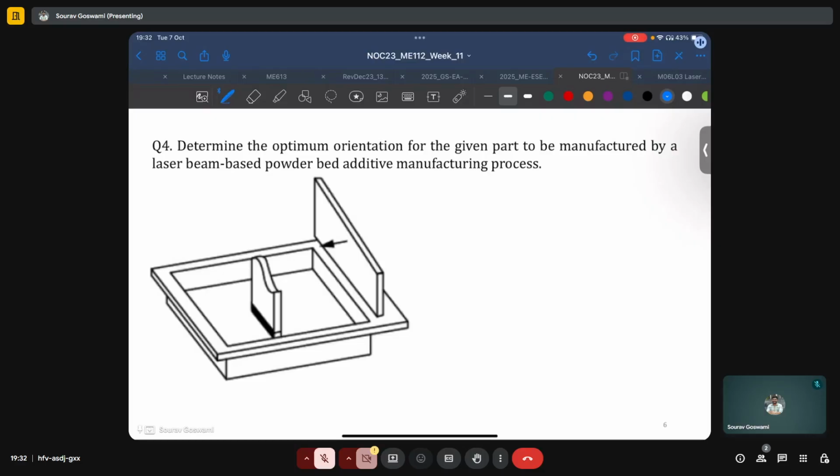One of the principles which we discussed during the session was that we should try to minimize the number of edges which are aligned exactly with the recoater blade. And the purpose for this was to reduce the surface area of the part in contact with the recoater plate at any given time. Here, the recoater axis and the part axis are parallel, and so this is of course not optimal. Further, we can see that in every pass,